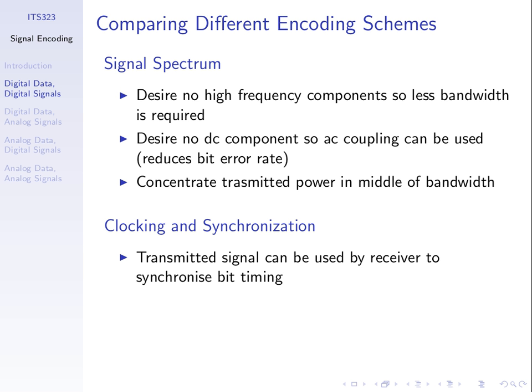That is, its clock is wrong. It doesn't have an accurate representation of time. What that does is introduces potential errors as we receive the signal, because the receiver thinks the first 0.8 milliseconds is the first pulse, and then the next 0.8 milliseconds, which takes us to 1.6, is the second pulse.